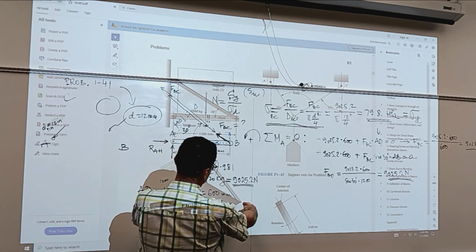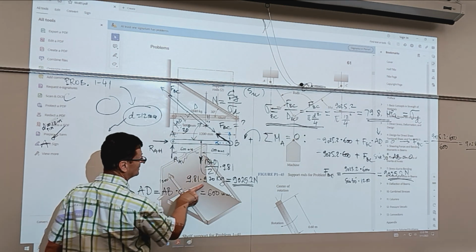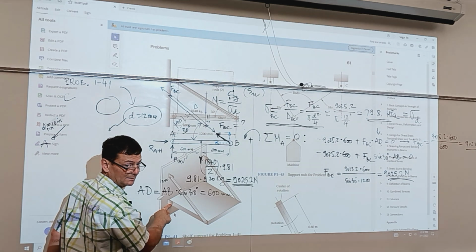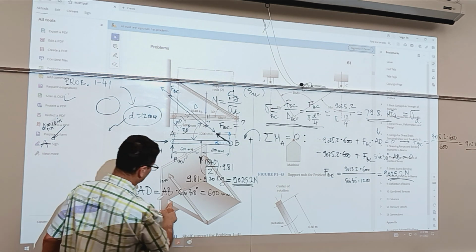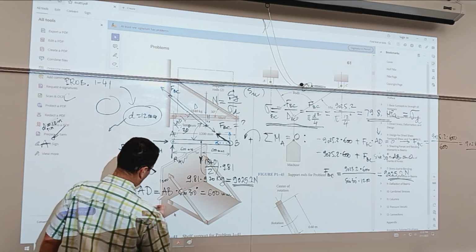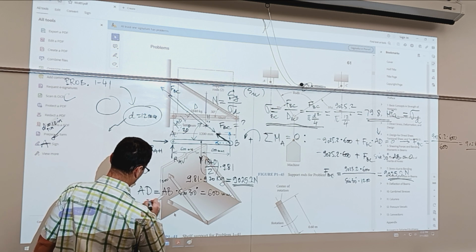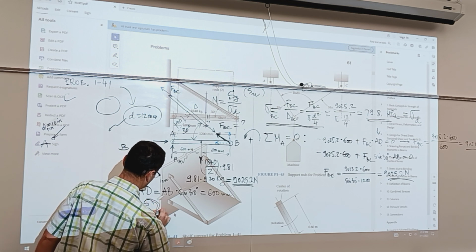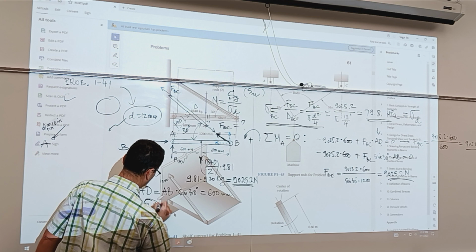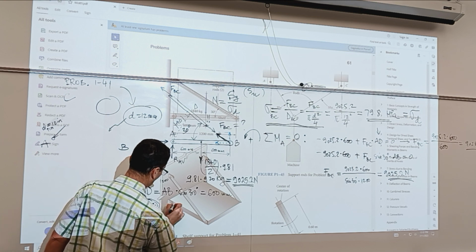They don't say how long it is. Having a hole that is this long might be an issue. So this is not the best design, I would comment. It might just be a pin that was mounted on a bracket and bolted.